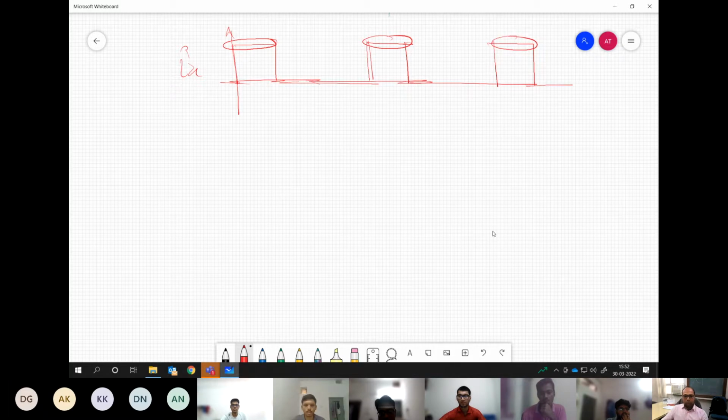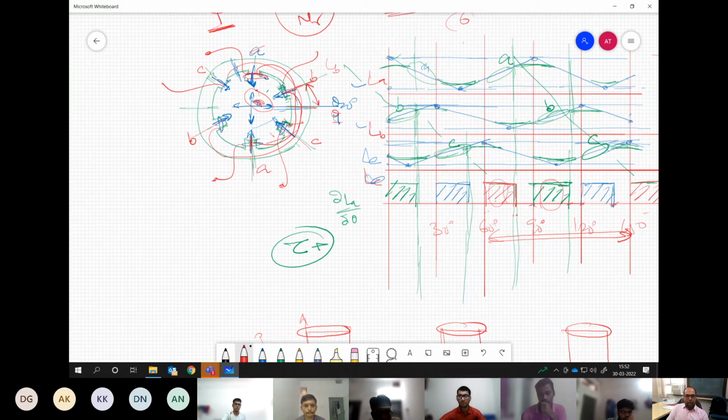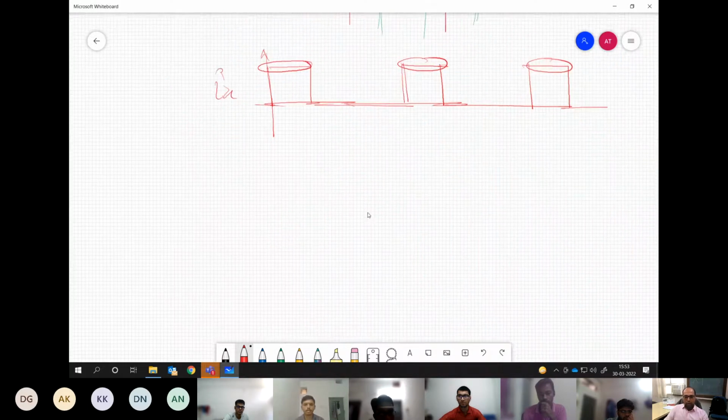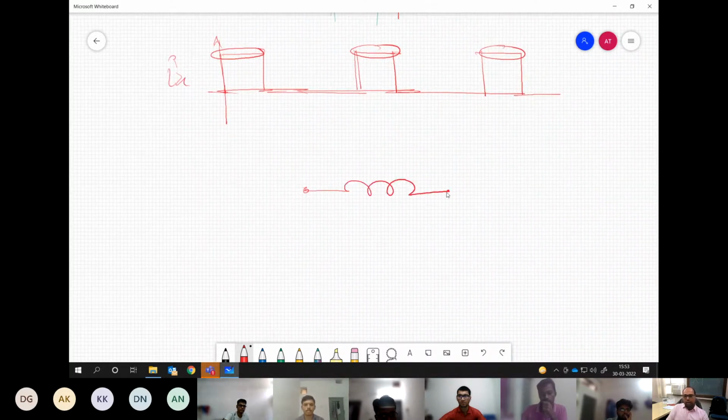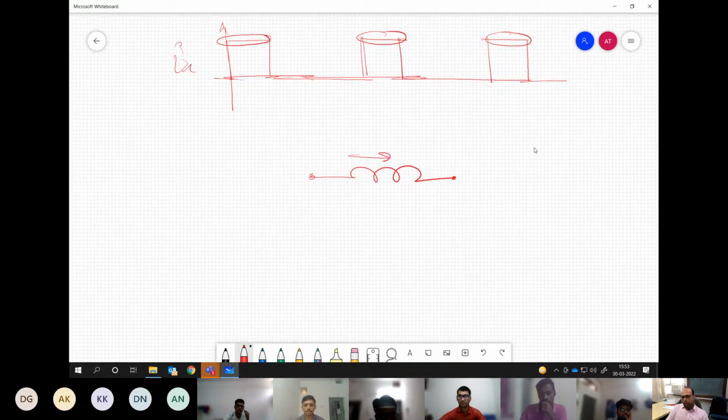Let us say first we need to model this. We have a coil for a given phase, let's say connected in series. So ultimately we have a coil in which we are trying to maintain a constant current value. Now this coil has a property: the inductance of this coil can change, because that's what is happening in the reluctance motor. The inductance is changing from minimum to maximum value, and that is why this is not a linear system. Understanding my point? Yes, sir. This is one problem.